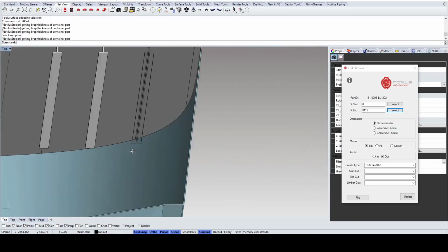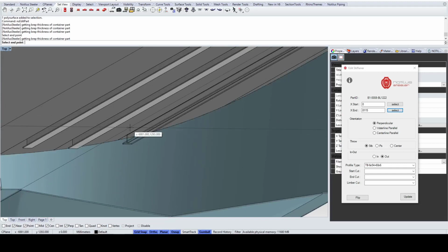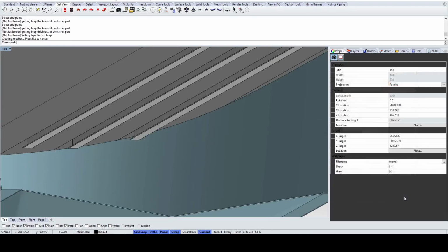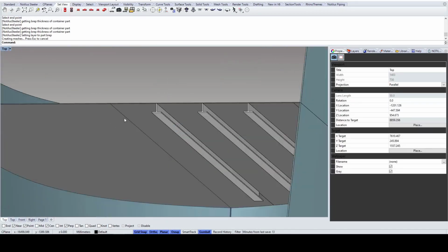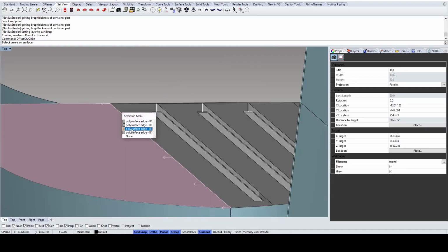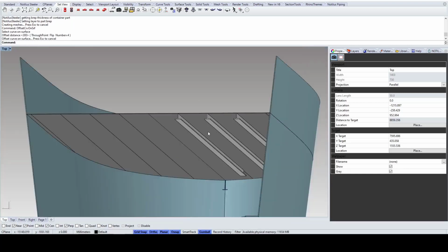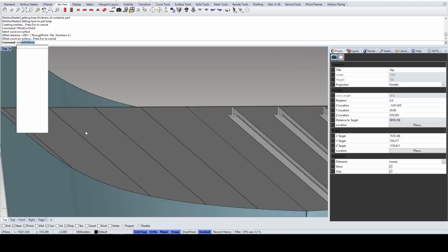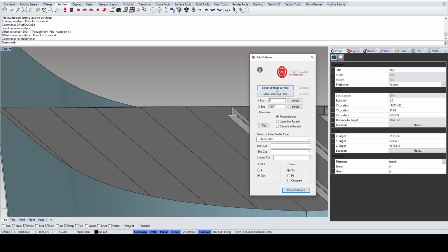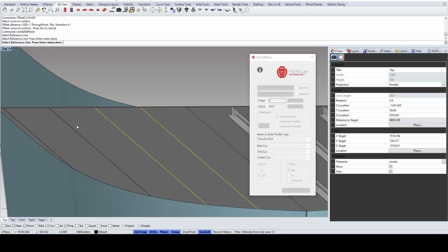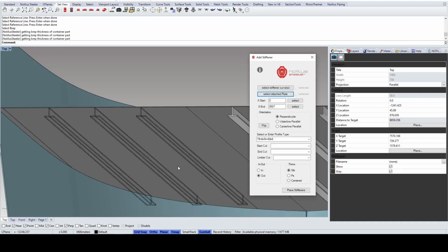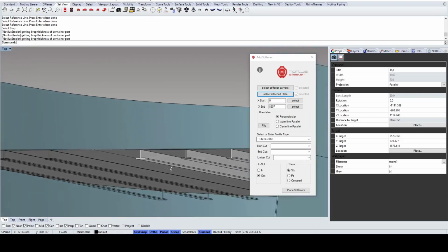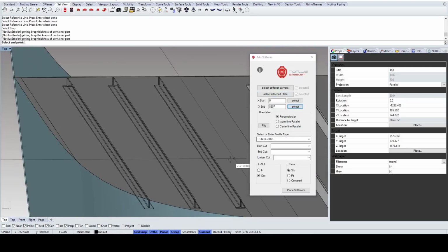Start and end positions of the stiffeners can be updated by selecting a point or entering a position value directly. Predefined cut types can be applied to stiffeners. Snipe end details can be used if wanted.